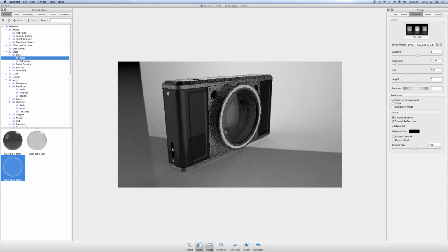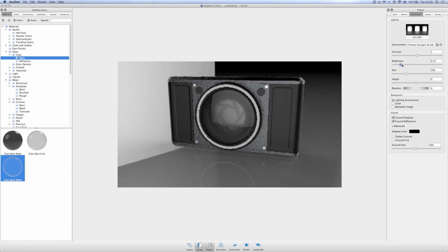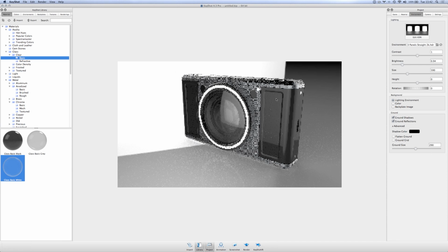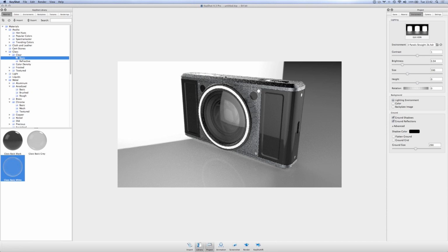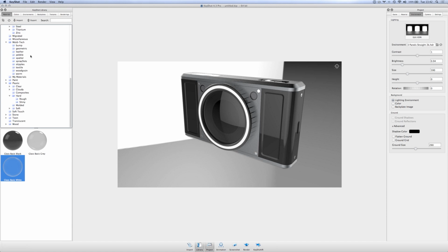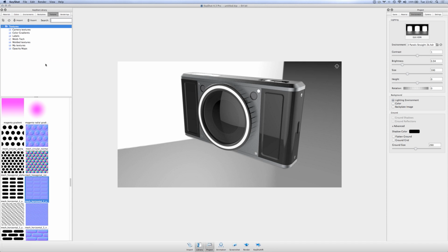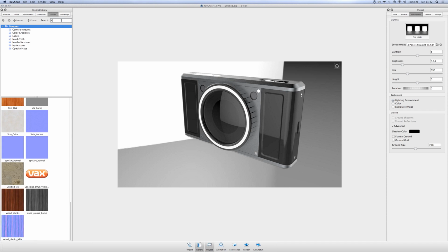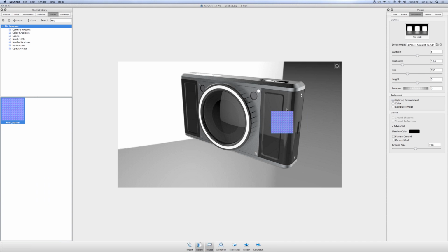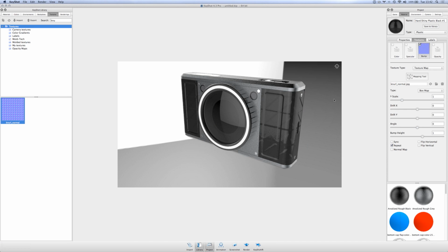Okay. All right, let's add a little bit more texture onto the grip here on our camera because it's looking really, really dark. Again, we'll toggle into performance mode, Alt-P, just so it's a little bit faster to work with. There's a question about a knurled texture, and yes, that's how we can create a knurled texture using those image maps before. So again, here's just our shiny piece of plastic. If I just type in knurl, drag that over to the part just like we did before. That's a normal map since it's that kind of purpley blue one.